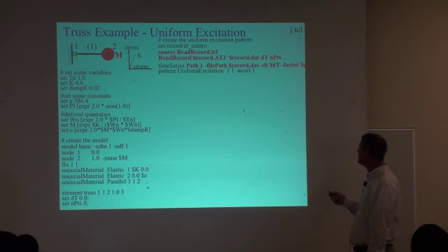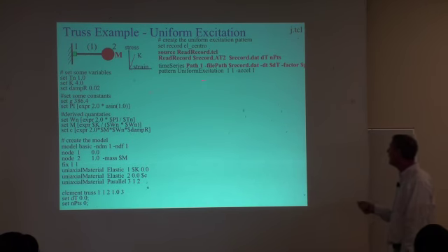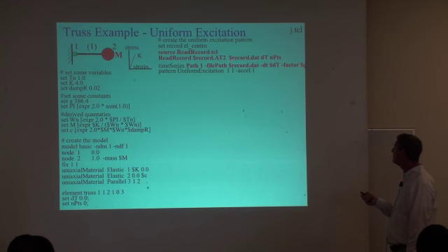So the procedure is in this file. Again, it's in this place you can download. And on this next line, read record, that's where I'm invoking this procedure. It's defined in the file. Whatever record I set, in this case I'm using El Centro. Let's set my record to be El Centro. The procedure is going to create a data file just containing the data points, and it's going to come back with a variable set for dt and the number of points.